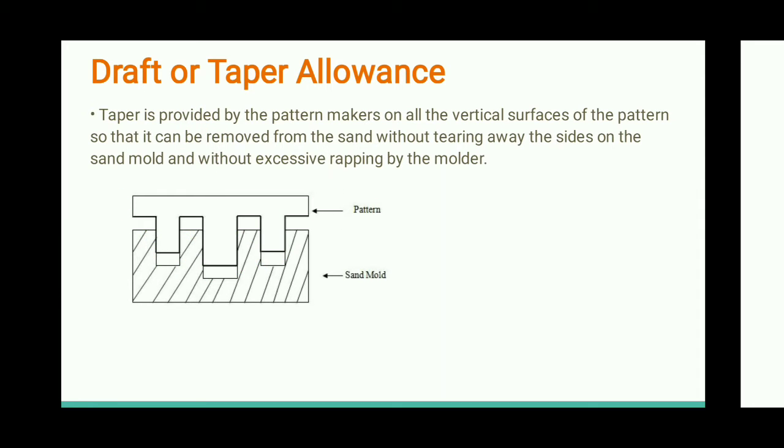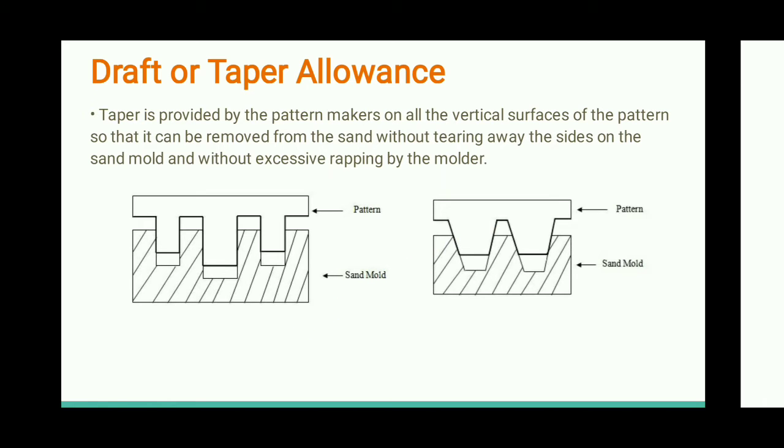Or another way is, if the vertical passages that we are using in the casting have a lesser diameter or lesser thickness, then it's very difficult to shake the pattern, because there may be chances of breakage in between.